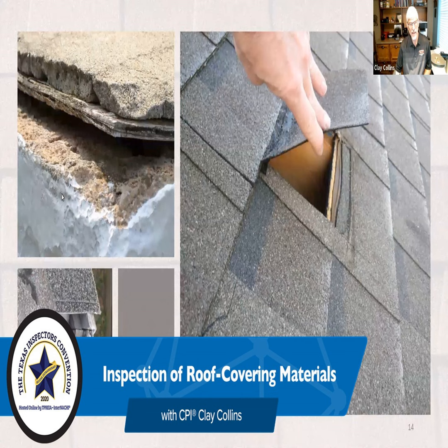Well, that's obvious, but you get into attic spaces. The one on the left seems to be out of focus. I think I must have been drinking. But you can still see that it was deteriorated. And you see the upper right-hand quarter, how badly it's deteriorated. Not only has it damaged the decking, but it's begun to damage the rafter there.